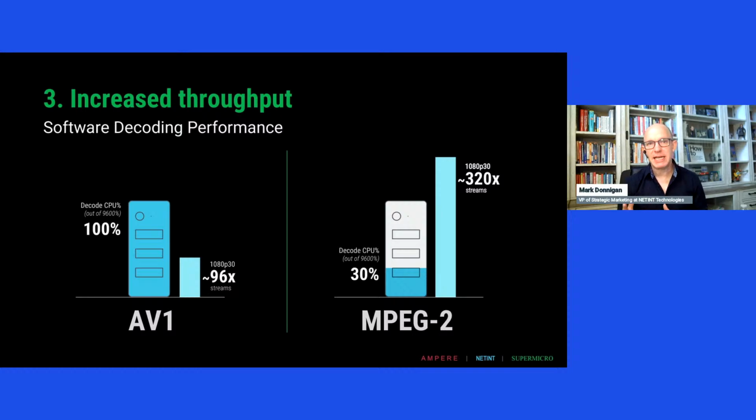So we were able to decode 96 channels. And again, the beautiful part about this is, remember, the VPU capacity is largely unaffected. So even though in this scenario it did utilize nearly 100% of the CPU, you still have the full capacity of the VPU because it's silicon, and the overhead just to communicate on the NVMe bus is minimal. It's virtually zero, so it's very low. So that is a really wonderful advantage.